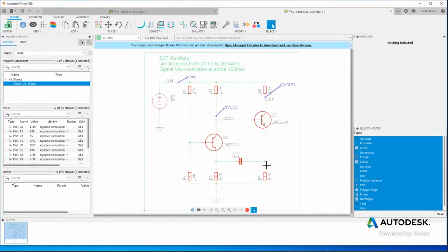Voltage will again start to rise, eventually cuts this transistor off. Voltage starts to drop here. Once it drops low enough for the transistor to turn back on, it'll turn back on and drop this one again. So they're basically flipping and flopping between each other. That's what we should expect to see.